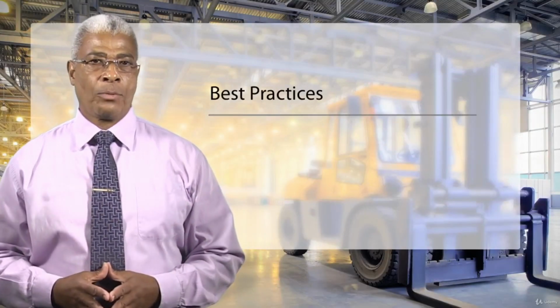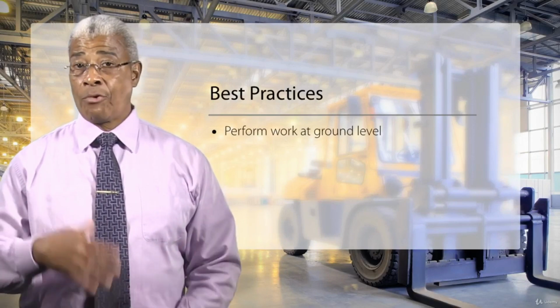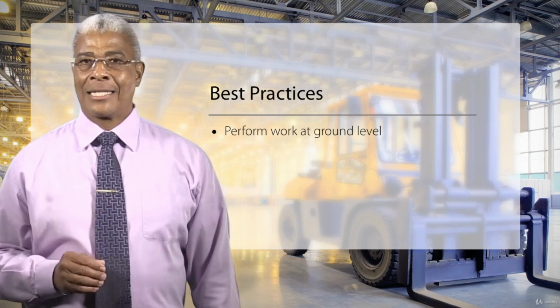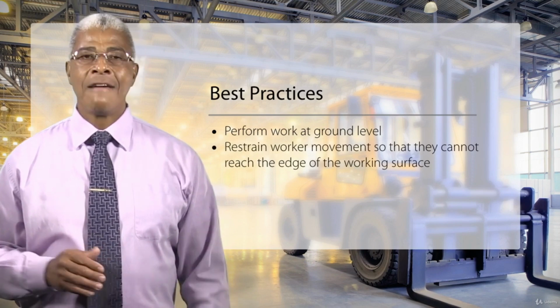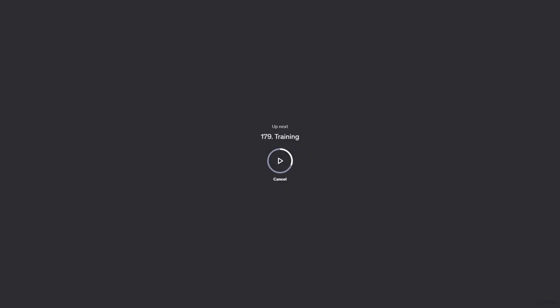First, whenever possible, perform work at ground level. For example, if prefabricated materials or sections can be created on the ground and lifted into place, use a crane or some other lifting device. Next, tie or restrain workers in a way that they cannot reach the edge of working or walking surfaces. Finally, use conventional fall protection that is OSHA compliant.